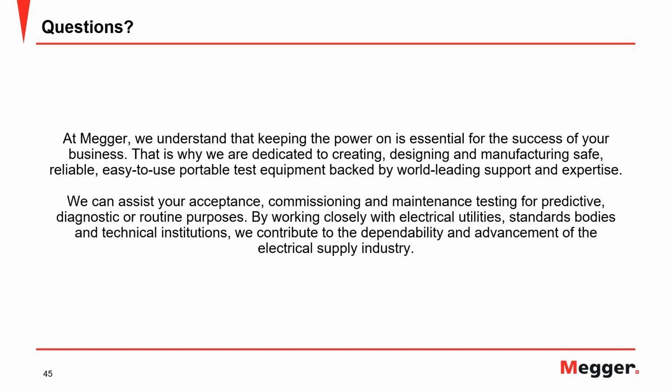So when we get into the frequency range of 1 hertz to 10 hertz, any increased conductivity because of the presence of moisture or contaminants greatly contributes to a higher value of a particular dielectric constant, which translates to a higher value of dissipation factor or power factor. And that increase in dielectric losses associated with the increase in conductivity translates to a higher value of power factor, which is why you see the power factor climb up drastically in the lower frequencies when you're dealing with a bushing which is in the early stages of deterioration.